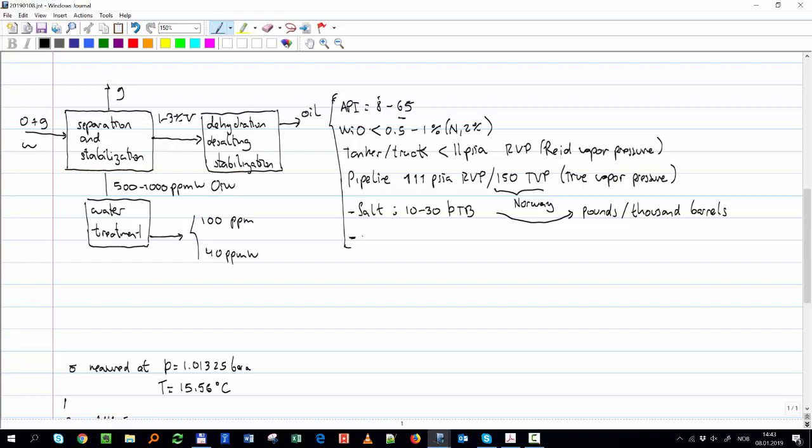And then, very important, the H2S. Okay? Have you heard about H2S before? Any of you? Yes? What did they tell you about H2S? They have to tell you, the only thing you have to know, you have to run away if you see H2S, okay? If you see a detector, H2S, you run away. It kills you very quickly.